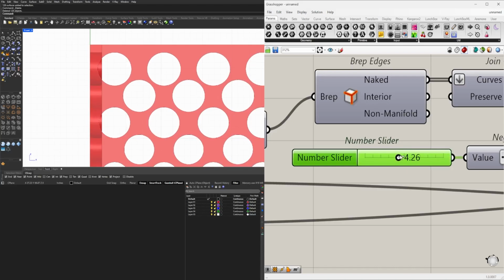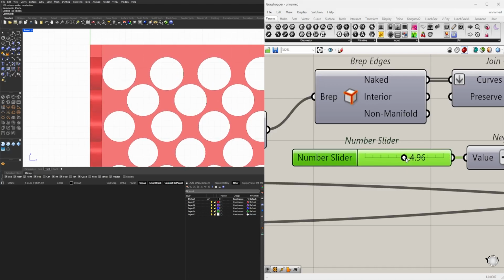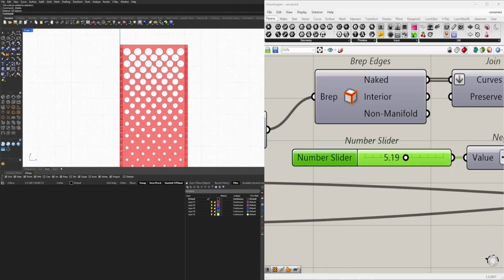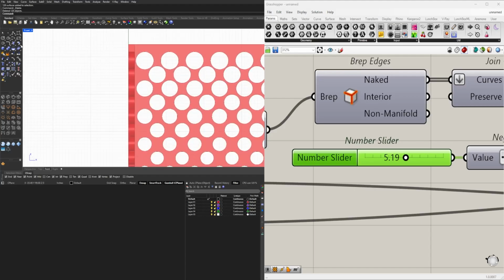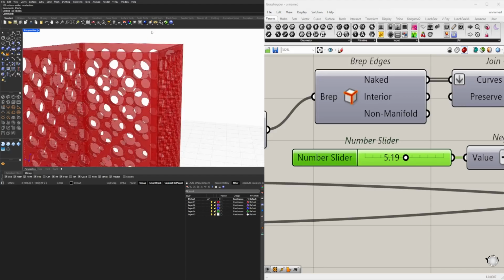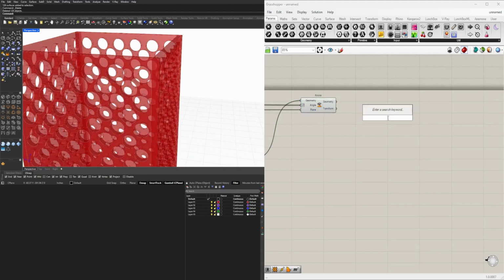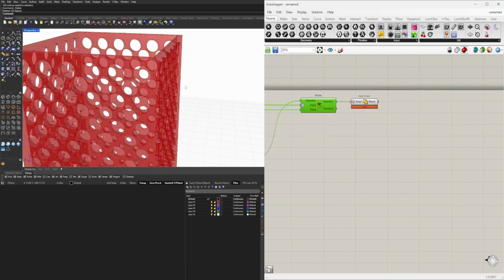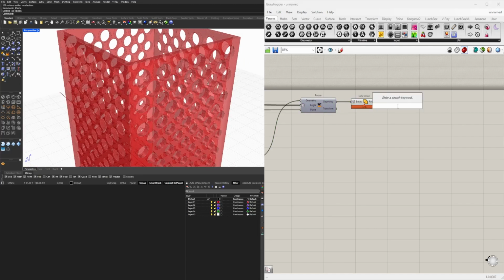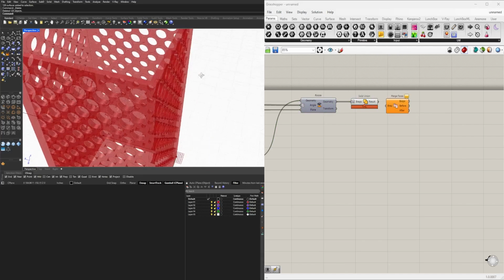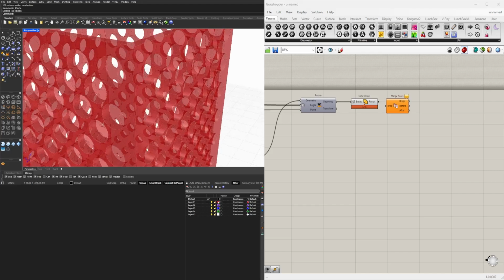So just keep in mind that if you're creating a large gradient like this, in some instances they will overlap, but if you make sure that the tolerances are right, then we can actually join those together using union. So solid union, flatten the input, and merge all coplanar faces, which will get rid of the crease here at the top as well.